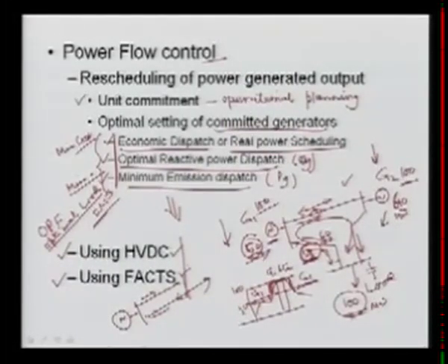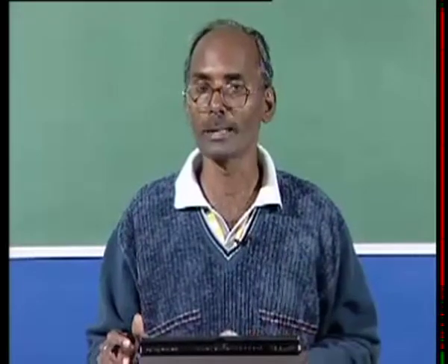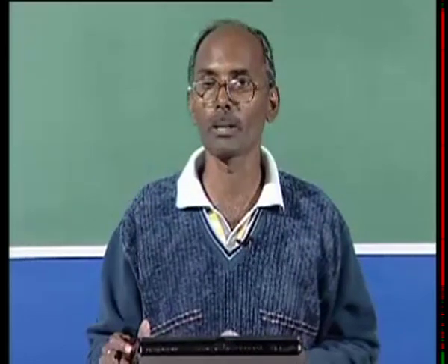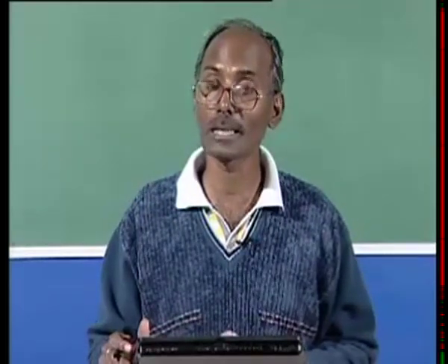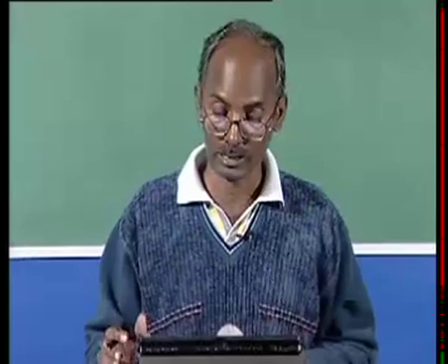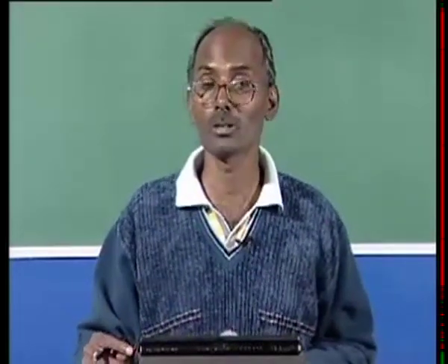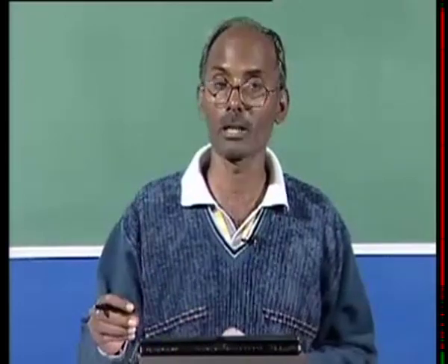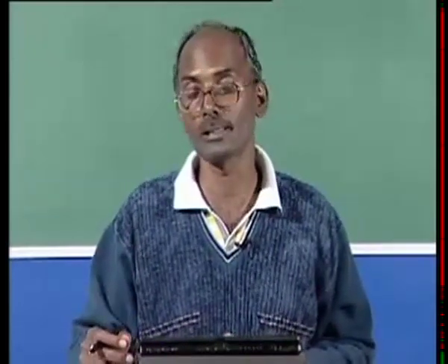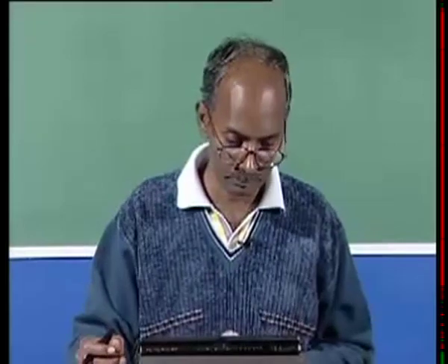About the FACTS controllers: they are nothing but flexible AC transmission system controllers or devices. Those are used in the power system to control the power flow, and thereby they enhance the power system performance, both static as well as dynamic. And already we have seen the STATCOM and SVC. We will also see a few FACTS controllers in this module, like your UPFC and the TCSC, the basic controllers.